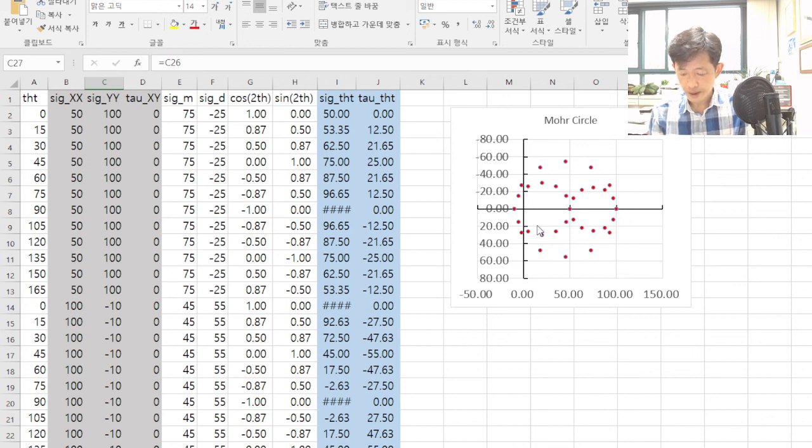Okay. And in the case of the UOE procedure, first we use a long plate, and then we weld them together. That's why in the second procedure we have a straight welding line here. So usually the welding line would include some defects. That's why it is very important to check the stress development in the welding line. Okay. So in class, I already discussed how to solve this problem.